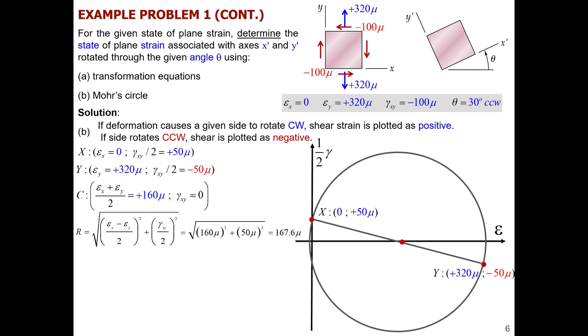All right, so then we can now go to calculations of our new state. We're going to rotate our system counterclockwise by 30 degrees. So we have theta here, and that means that we'll have double theta in our Mohr circle space, not in the physical space. Remember that angles double when we work with the Mohr circle. So that will be our new state, where our x will go to the x prime face and y prime face. So that's x prime face, y prime face, and those will be the coordinates.